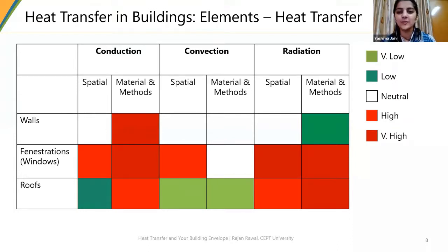Next question: how to take care of condensation while employing natural air circulation with radiative cooling by engineering design of the radiative cooling system, or are there other airflow control options? No, you need to maintain a temperature at least 2 degrees higher than the dew point temperature, and with natural means you can't really do that. So you will have to deploy some kind of mechanical means and control for both.